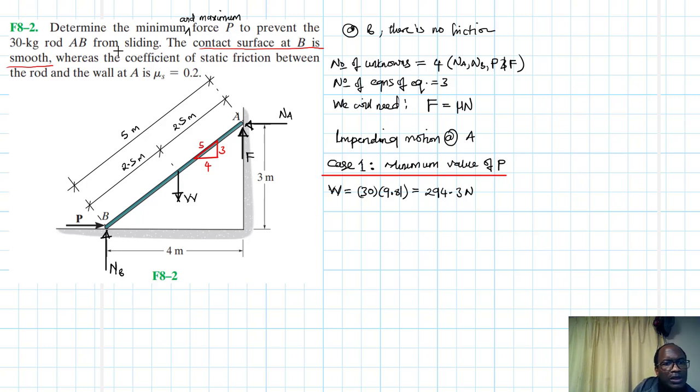So like we said, this is the friction force. Okay, we already have that equation. Let's sum up all the forces. So sum up forces in the x, in the y, and we'll take moments. So let's say summation of forces in the x direction equal to 0, in this direction being our reference.